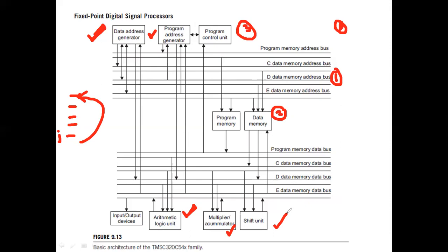How are you going to do it? You are not going to do it the normal way. You will usually be using shifts. You will realize that whenever you are doing normal multiplications or divisions, you will not usually multiply by 5 or divide by 7. You rather multiply by 8 or 4, or divide by 8, 16 or 4, so that those multiplications can be carried out by simple shift operations. That's where a shift comes into the picture.